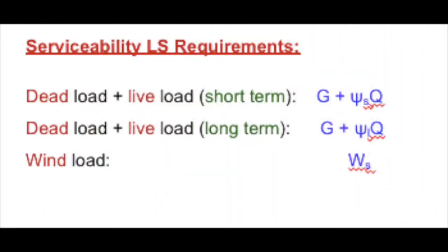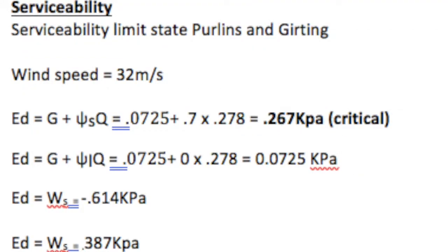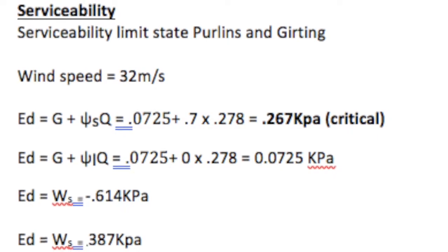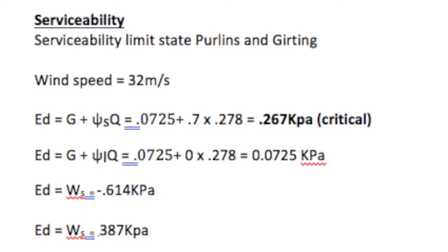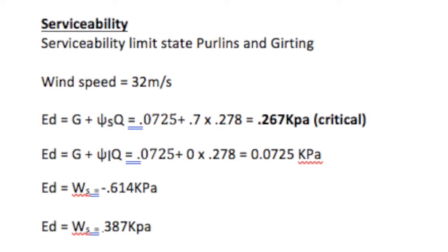In addition to the ultimate state check, a service limit state check is also completed. The aim is to prove that under the action of unfactored loads and whilst applying certain magnitudes of force, the structural behaviour complies and doesn't exceed the serviceability limit state design criteria values. We use the formulas as found in the Australian standard to solve for this.